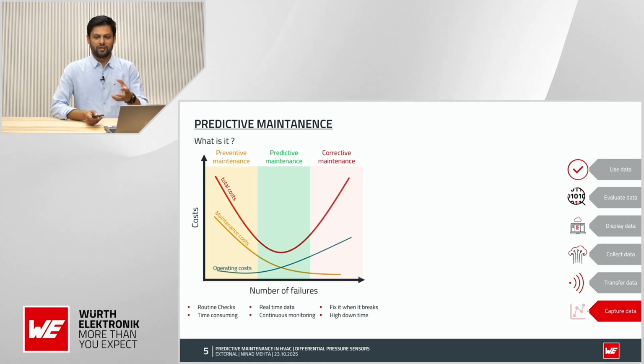And as mentioned, how can we do this? We can do this with sensors, monitoring different environmental parameters. To monitor pressure, you can use a pressure sensor. For humidity, you use humidity and temperature sensors. And to check, let's say, motor vibration, you can use a 3-axis or 6-axis accelerometer and gyroscope.